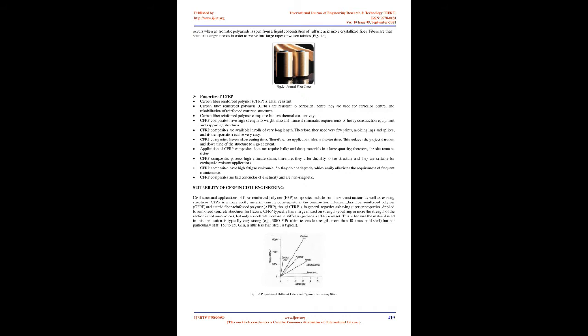Beams are load-bearing structural elements that are designed to carry both vertical gravity loads and horizontal loads due to seismic or wind. Structurally deficient beams fail during such events. There are mainly two types of failure of beams, i.e., flexural and shear. Hence, the strengthening of such beams is needed in flexure or shear or both zones, and the use of external